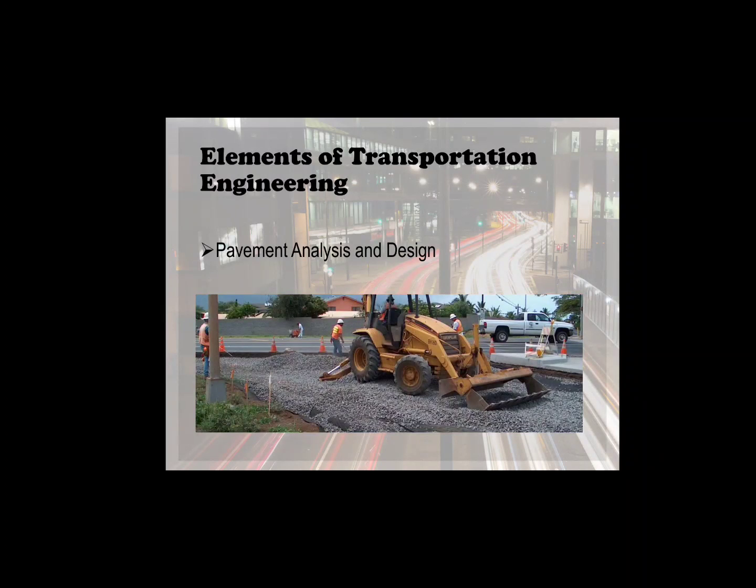Pavement analysis and design. Pavement design deals with the structural design of roads, both bituminous and concrete, so asphalt and concrete, commonly known as flexible pavement and rigid pavements, respectively. It deals with the design of paving materials, determination of layer thickness, and construction and maintenance procedure. The design mainly covers structural aspects, functional aspects, drainage.